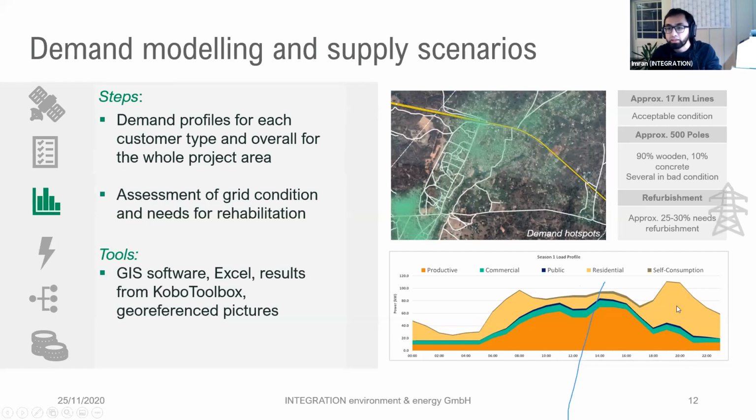And this gives you an idea that, you know, just a PV-based system is not going to work for you. A typical PV profile is during daytime. So you need to think about options with a nighttime supply, either via batteries or diesel generator or grid supply. And that awareness helps you to get a first idea of what the generation supply could look like.